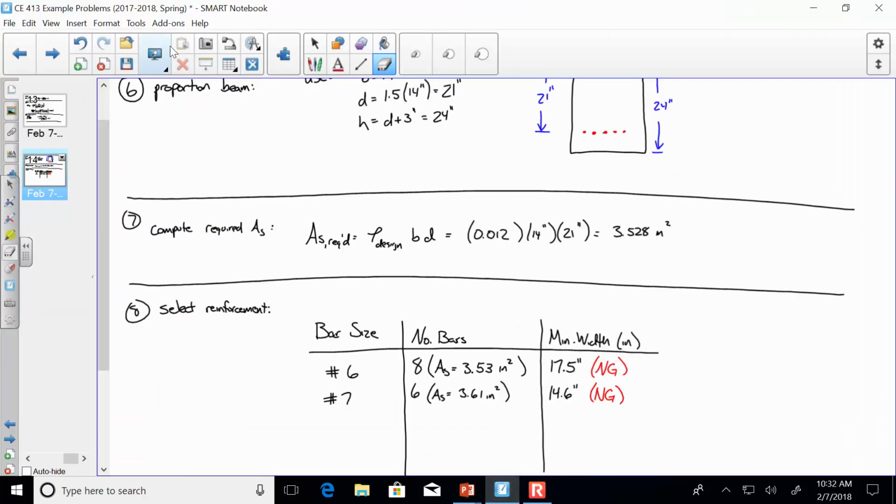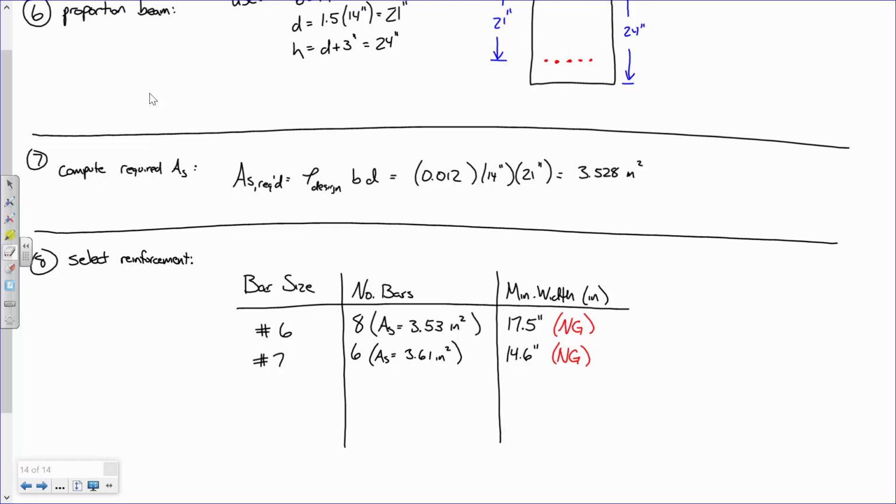All right. So everybody's sort of seeing what I'm doing here? Okay. So number 8s. Okay. 5 of them. So how much steel is that? Now, what's the minimum beam width for 5 number 8s? 13.25. 13.3. So this is a viable option, right? Don't really have much cover on this. Well, no, we're meeting all our cover requirements. That's incorporating cover on the sides.